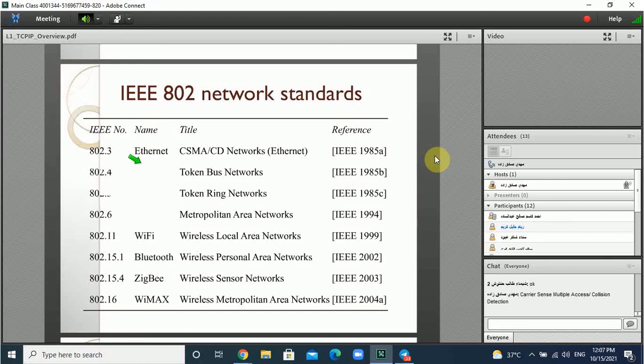Yes, collision occurs when, for example, two or more computers want to send a message on the bus. When a collision occurs, no computer can send a message. After a random time, each computer can try again, and the one that sends its message earlier wins.